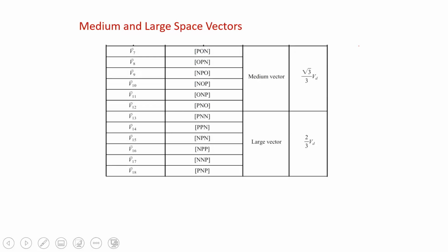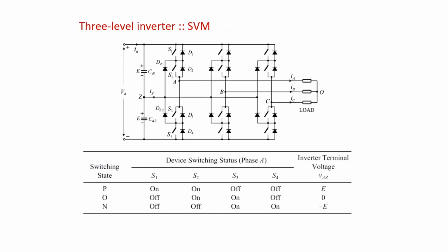So in the previous class, we started discussing the neutral point voltage deviation, especially in diode clamped multi-level inverters. What we mainly observed is that current is flowing into the neutral point. Therefore, there will be deviation in the charging and discharging of the capacitor voltages, right? This deviation will introduce a DC offset in the output voltage waveform.